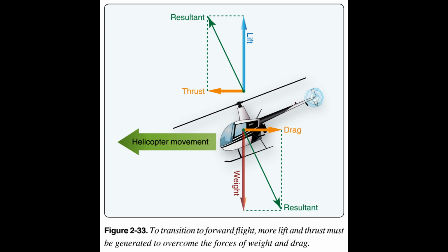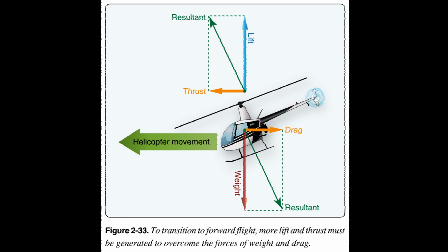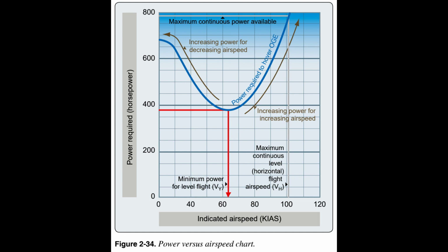End of page 2-18. Once straight and level flight is obtained, the pilot should make note of the power and torque setting required and not make major adjustments to the flight controls. Figure 2.34. Airflow in forward flight.